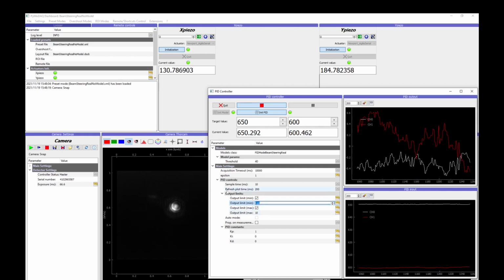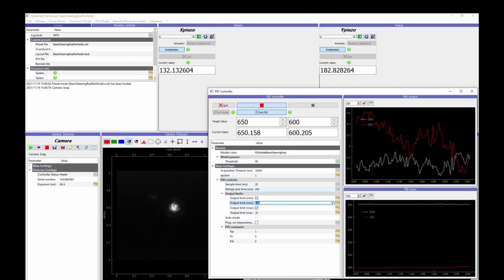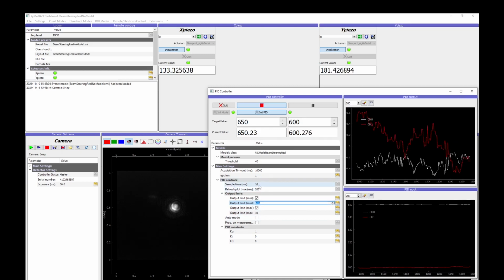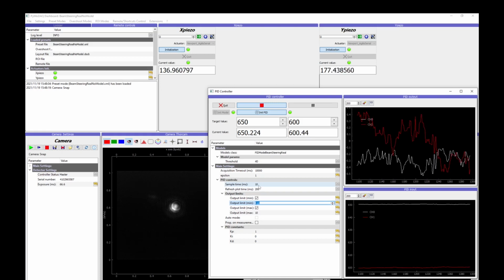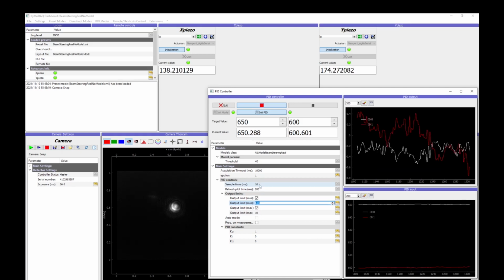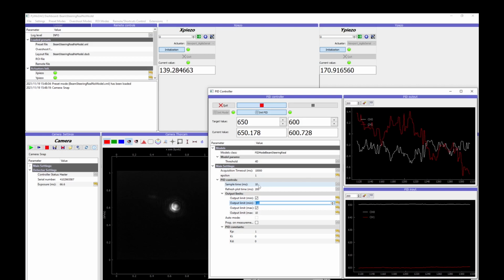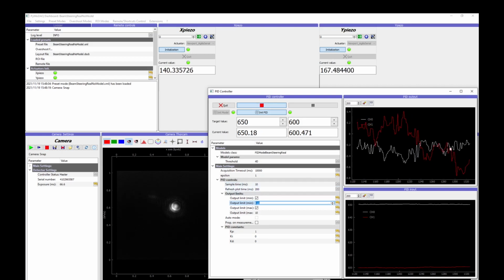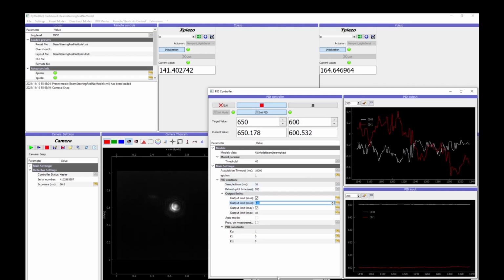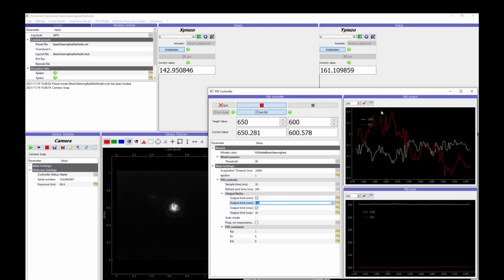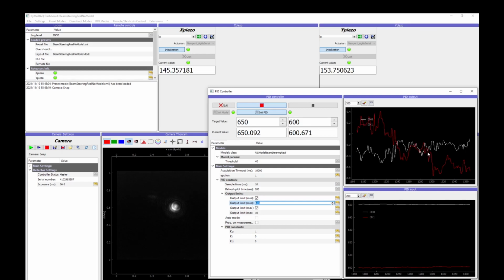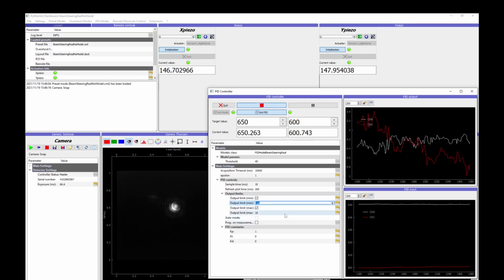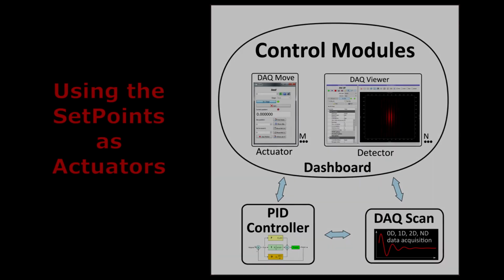So that's about the limits. Here, there is some other controls. Here, sample time, it's a time at which it's refreshing the PID loop. Well, if it can, if it's not limited by the measurements or whatever. And here, this 200 is a refreshing of the plots here. So that's mostly it for the different controls, and basically use these limits wisely depending on your system.